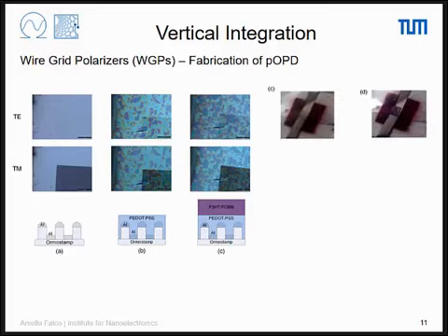And now we can see here a picture. I'm sorry for the bad quality, but I just took it with the cell phone, and I put the polarizer in front of it. If you align the polarizer with the grid lines, you would have like a plain aluminum layer, basically. So the light does not pass, it's reflected back. While if you go on a TM mode with the polarizer in front of the camera, you can see that it opens up this clear optical window. And that's how it works.